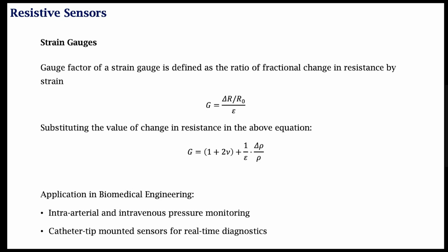Another application can be, for example, in our lab, we use what are called 6-component force torque sensors for measuring fingertip forces. These sensors are essentially silicon strain gauges, 3 silicon strain gauges mounted in 3 principal directions and calibrated to measure forces and moments applied in these 3 directions and about these 3 directions.